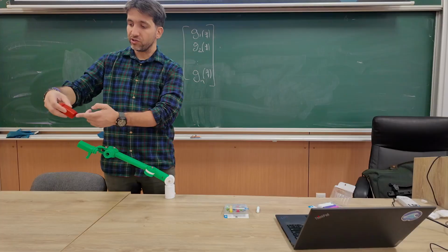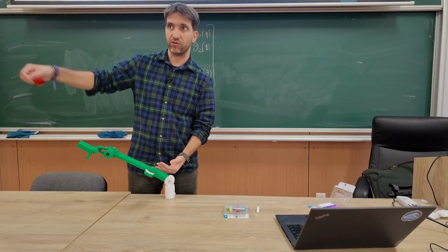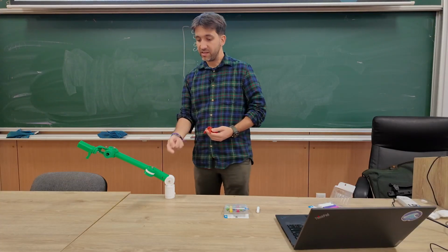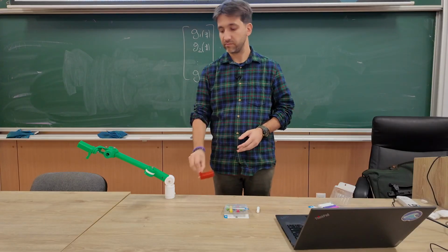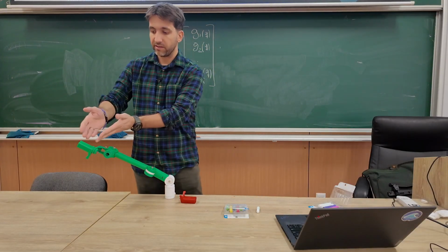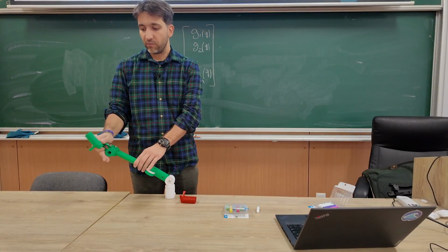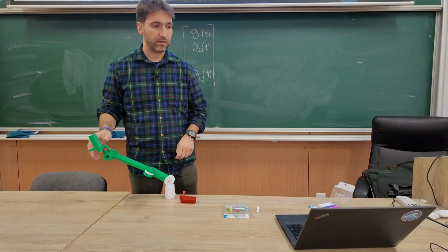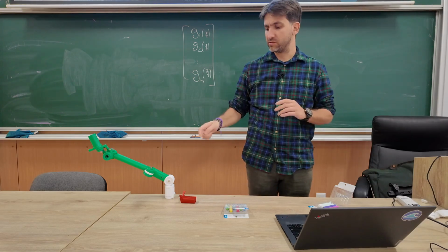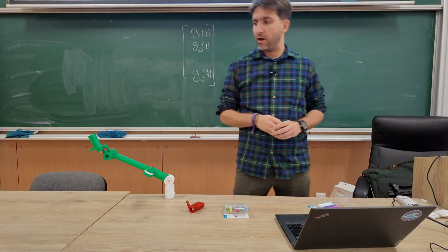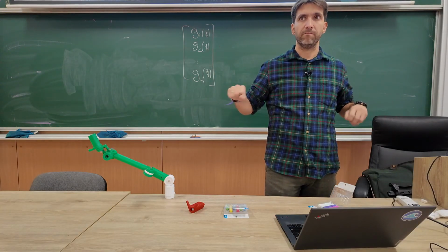So if this joint needs to stabilize this motion, then it has to counteract this torque, this force that is being generated. And this has to do with the velocity of rotations of all the joints, right? See, this joint affects other joints. And the other way around, like if this one is moving in some way, it also generates torques here. And it's the same thing with acceleration. That's more difficult to demonstrate. The point is that joints don't really move independently, right?